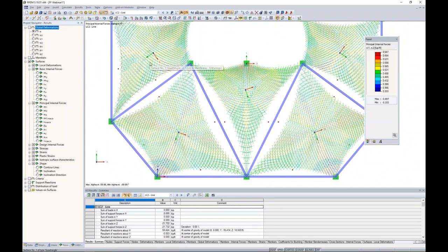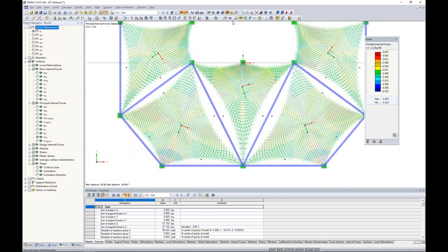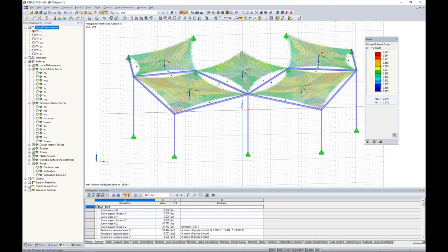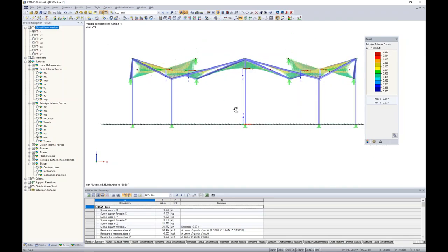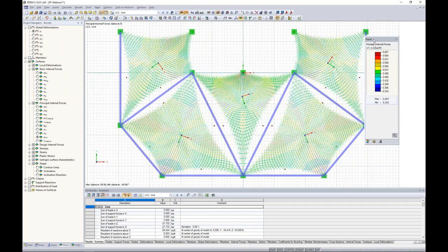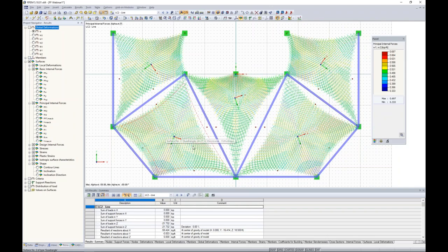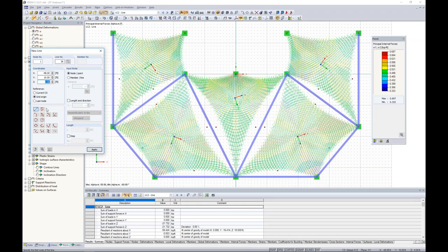So how do we orient the local axes of these members to make sure that they're taking the high tensile forces? How we do this is I'm going to turn back on my grid down at the bottom, and I'm going to uncheck the option for my user-defined grid, and we change this in the XY plane. So now we're just looking at that drawing grid at the bottom of our structure. We probably want to take a screenshot here, or maybe we can just approximately remember which way these high tensile forces are spanning, because once we draw a new line element here, which is what I'm about to do, the program's going to suggest that I have to clear my results in order to change any type of the geometry within the model. That's not a problem.